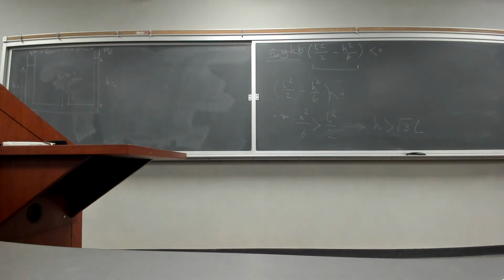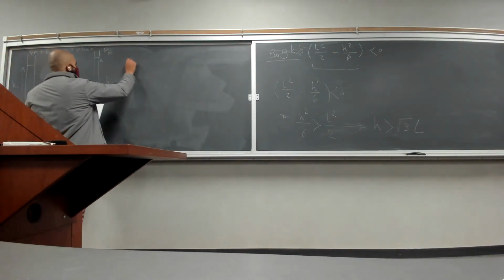So that's one thing that you have to keep in mind, that we are not dealing with gauge pressure here anymore because we have the absolute atmospheric pressure, right? If you were to calculate the pressure, you're dealing with absolute pressures. Or you can always calculate the gauge pressure and just mention that you have calculated the gauge pressure, right? You just have to make sure that you are clear on this. Okay, so we have this type of manometer, and we have 2 different situations.